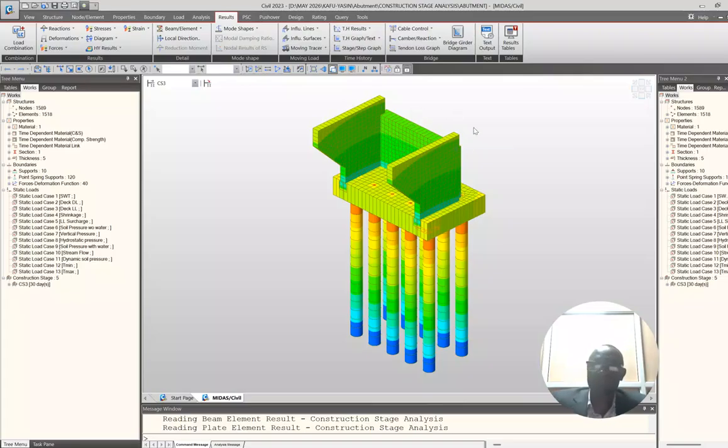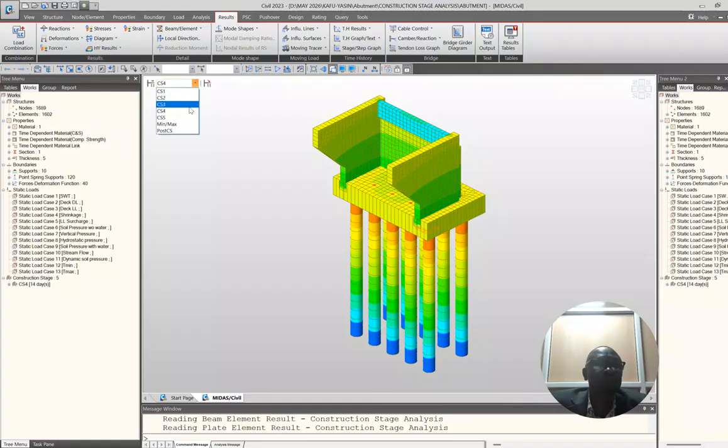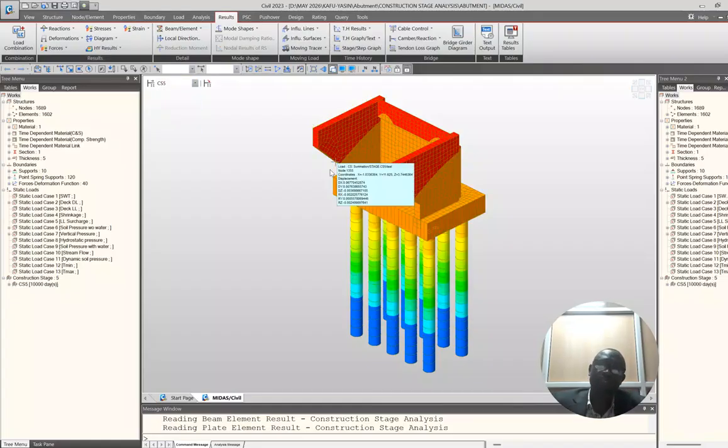Then stage 3 is when you have all these in place. If you are to do the launching of the deck girders, you need a drive until you do all the launching. All the girders are in place, then you put this reinforcement up and the ballast wall is constructed. That is why you are able to see what we have. Then the last stage, which is stage number 4, the weight continues. Then if it is all in place, that is stage 5. So this construction is done.